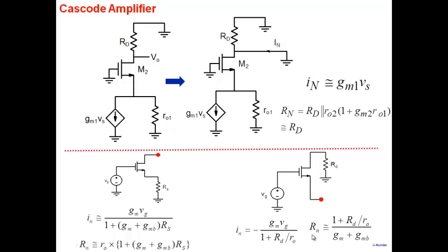Right? So either you'll be taking a voltage at the gate, at the drain, or at the source, and you'll be building Norton's equivalent. Therefore, these two results which you have already derived will be very useful. Once you memorize these two results, you don't have to do a direct small signal analysis by substituting the model. Just use these two results, and you can analyze all complicated amplifiers with 10 transistors and so on, which hopefully I'll show you later. These two are very powerful results.